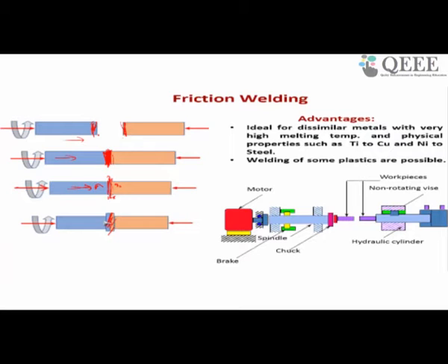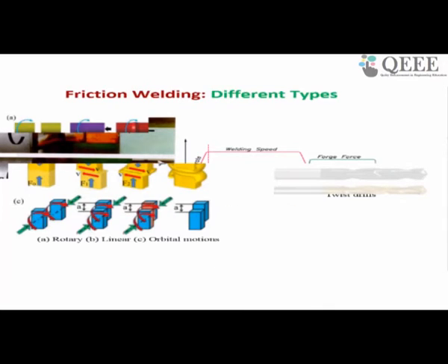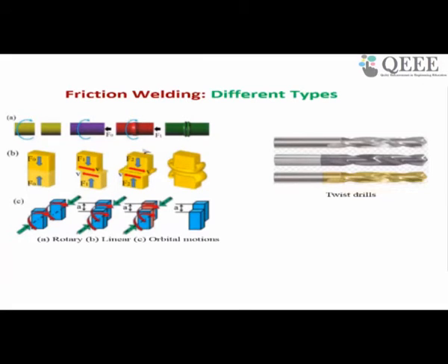There are different kinds of friction welding. This is called radial or orbital friction welding, and by using this kind of process you can join any type of symmetrical components. It has wide application. There are three classes. We discussed this class, called rotary friction welding, where you induce friction between two parts. That friction softens the interface. Then you apply force to obtain the deformation.